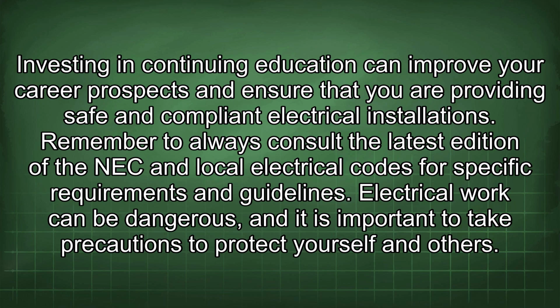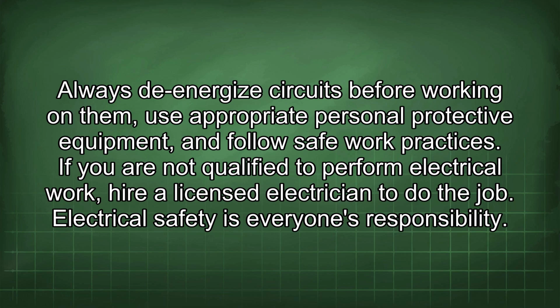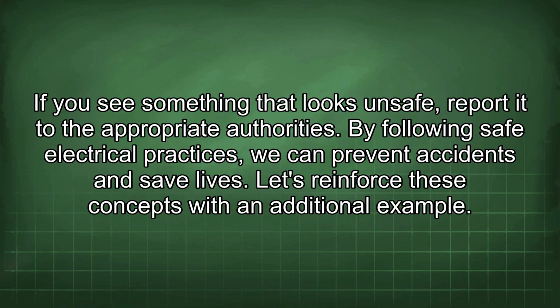Electrical work can be dangerous, and it is important to take precautions to protect yourself and others. Always de-energize circuits before working on them, use appropriate personal protective equipment, and follow safe work practices. If you are not qualified to perform electrical work, hire a licensed electrician to do the job. Electrical safety is everyone's responsibility. If you see something that looks unsafe, report it to the appropriate authorities. By following safe electrical practices, we can prevent accidents and save lives.